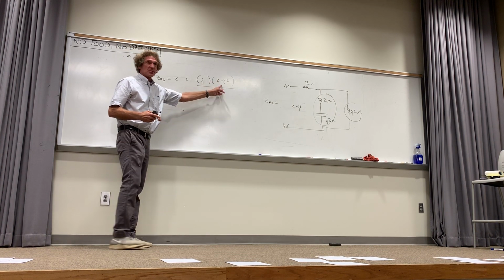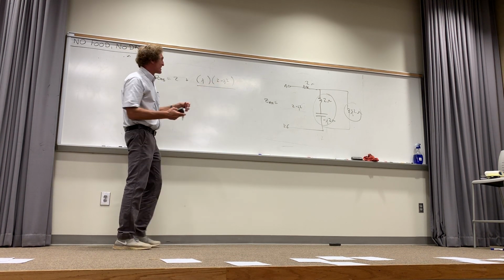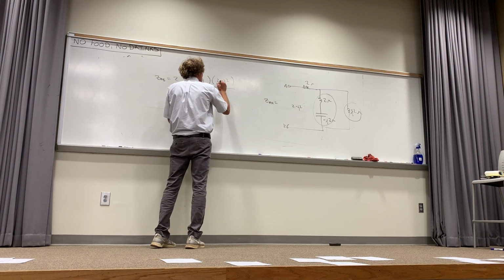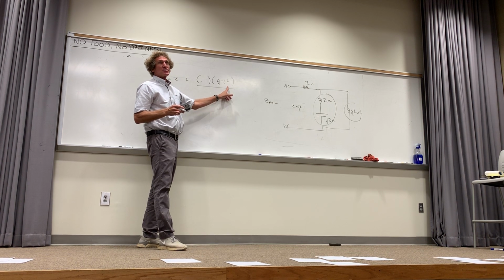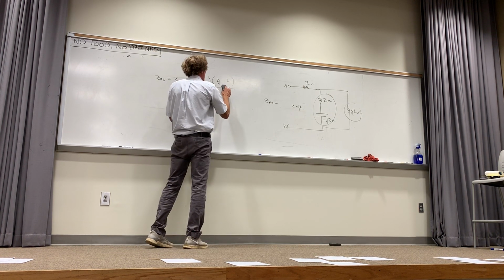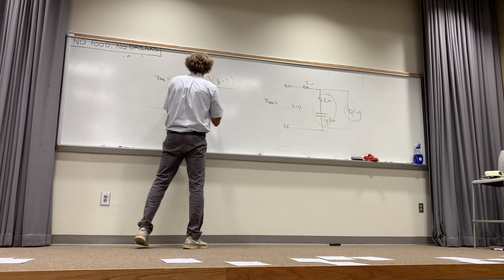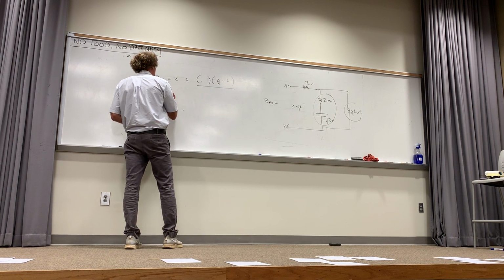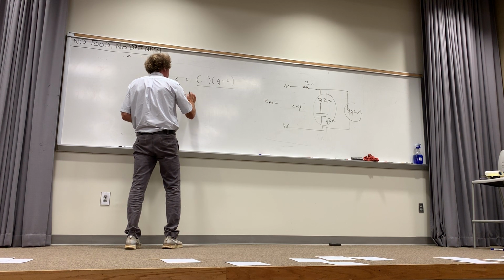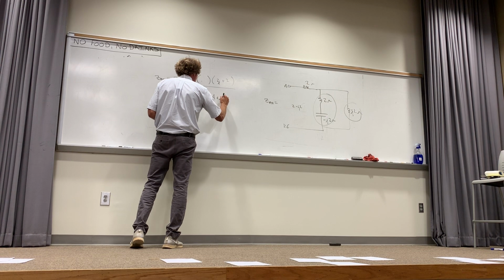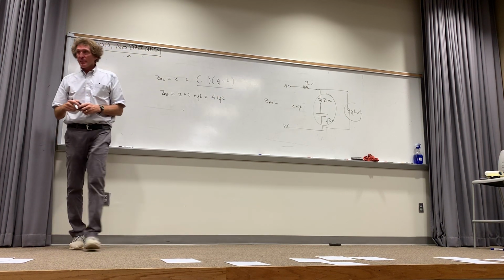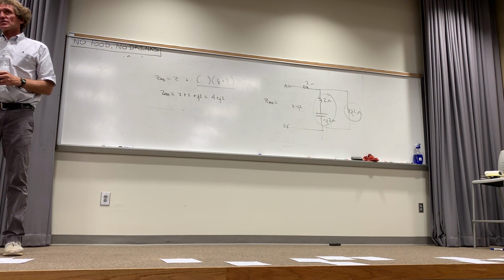What is J times 2? 2J. Right? And what is J times J? Well, square root of minus 1 times square root of minus 1 is minus 1, right? With the minus in front of there is plus 1. So my ZAB is actually 2 plus 2 plus J2, or it's simply 4 plus J2. You all see that? How many see that right there? It is as straightforward as it looks.